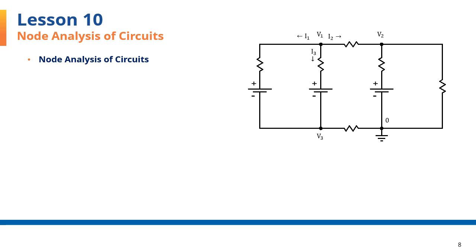You can see the assignment of index current variables to node 1 branch. Those are right here, I1, I2, I3. The order in which they are assigned or numbered and the direction for each does not really matter, but I typically take them to be outgoing currents from the node. I'll explain the rest of the steps with the circuit fully specified and in the process of completely analyzing the circuit.